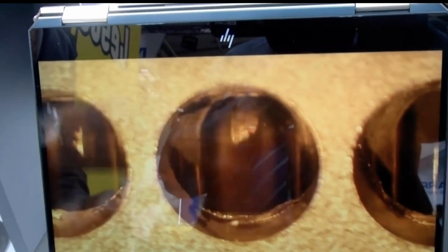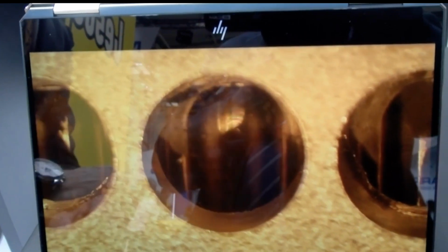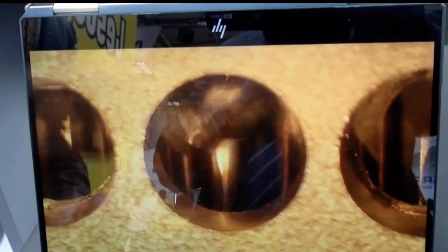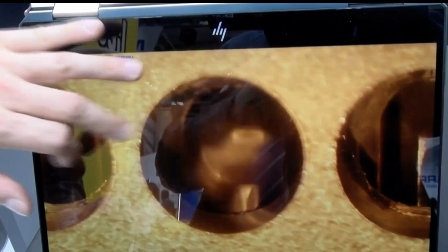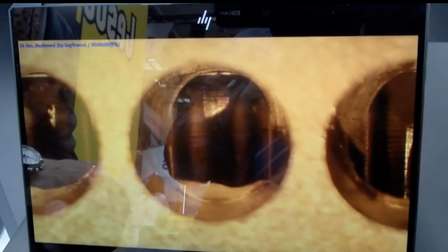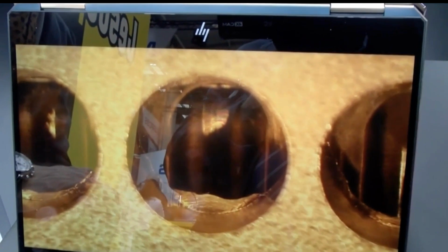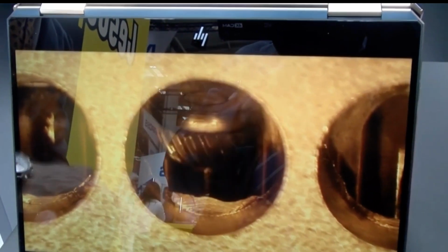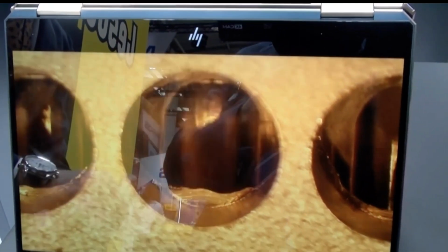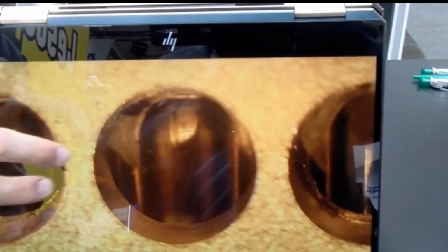And now this is being used in an electrical rotary grinder, and the operator is just moving the tool very easily up and down. So we can see it here again. Cutter comes into the hole. We start the tool up, and now the operator is making a very light filing motion, so only the burr is removed and no damage is done anywhere else.